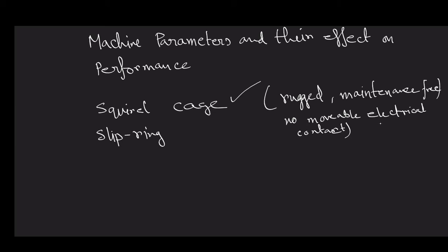It invites additional periodical maintenance cost, because you have to replace the brush periodically. However, if there is no such movable contact and every power transfer takes place through induction, then you do not need that kind of periodical replacement.